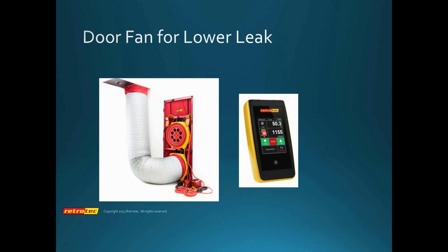We simply set the pressure across the suspended ceiling to 0 while measuring the enclosure leakage, and we get rid of the old-fashioned step that we used to have of testing the tiles with smoke to see if the smoke was going up or down. This reduces the time it takes to do this test and reduces the technician requirement from 2 down to 1. Sometimes we'd even have 3 or 4 people doing this test. So it makes the test much easier to do.